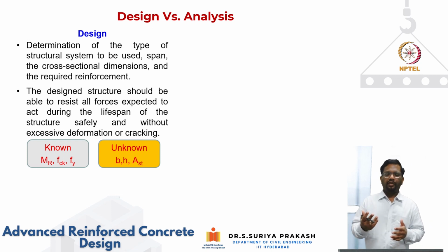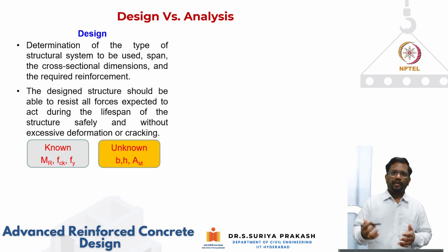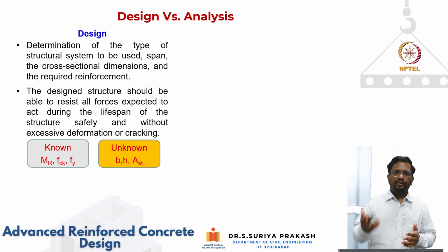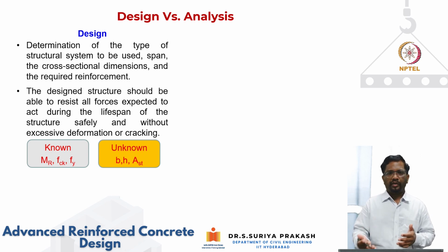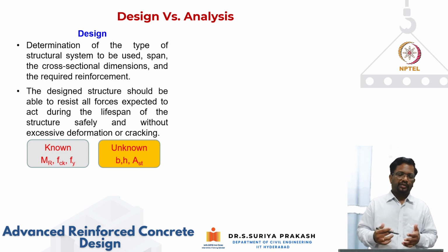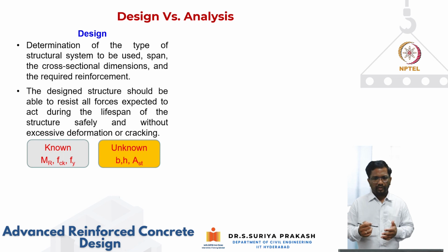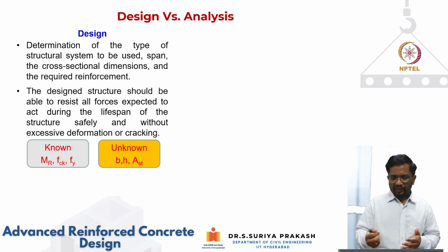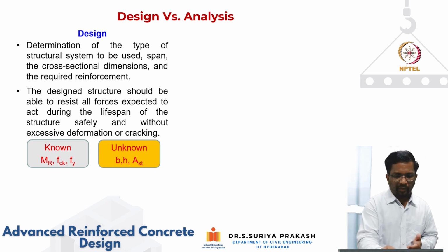So what is that internal force distribution? Basically to find out the variation of your shear force, bending moment, axial forces, and torsion on the structural elements that you are designing. In design, usually we try to find what type of structural system to be used, what should be the span, and what should be the cross section dimensions and the reinforcement.